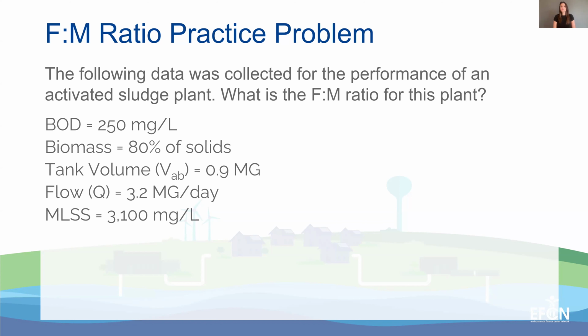Just real quick, again, when we're doing a word problem, we figure out what we're trying to find first, which is my F to M ratio. We know that to find my F to M ratio, I need the living component of my solids. So that'll bring up my next poll question, Matt, which is what is the MLVSS for this problem? So what is the living portion of that total suspended concentration?